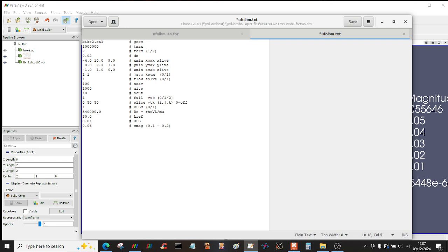Now this is lattice velocity. Now you shouldn't really need to change this much. You can leave it at 0.04. You don't want the flow solution to go above 0.33 anywhere. So 0.33 is the highest value of velocity that you want to have in your flow solution, otherwise it will become unstable. And I think that's why we use quite a low value for the lattice velocity, so that you prevent the highest value of the flow from ever being above 0.33. That's kind of like a stability limit.